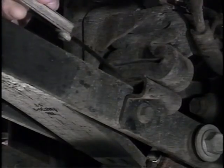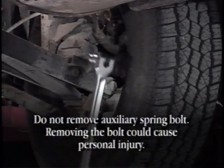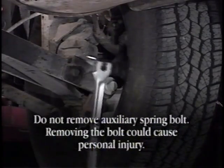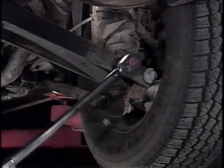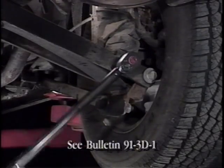If clearance of more than 0.02 of an inch is found at either bracket, carefully loosen the lower bolt a maximum of 2 turns and allow the lower auxiliary spring bracket to reposition itself against the spindle rod. Then retorque the spring support bolt to 36 pound-feet. That should prevent the noise from reoccurring.